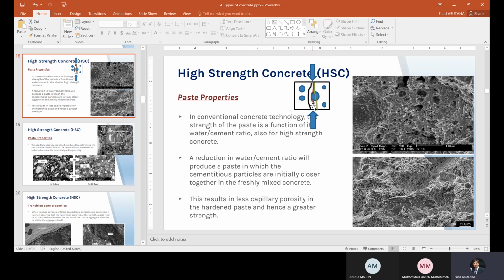You don't just take care of 2 and leave the 3rd, because no matter how much you improve the cement paste, or how much you improve the bond, if you are using weak aggregate particles, the failure will easily go through the particle itself and the whole concrete will fail. So the concrete will fail as long as one of the 3 parts fails. The weakest one will be the reason for the failure of the total concrete.